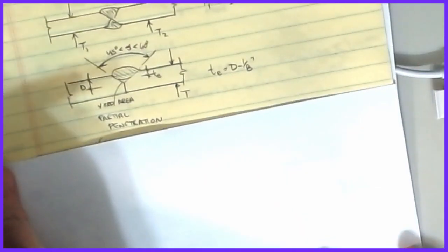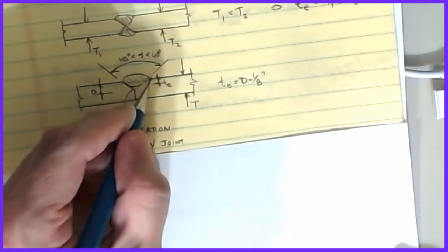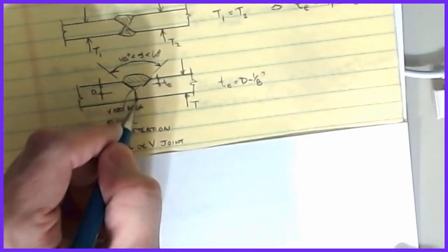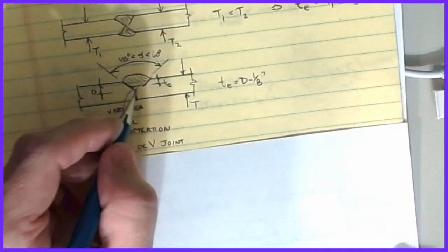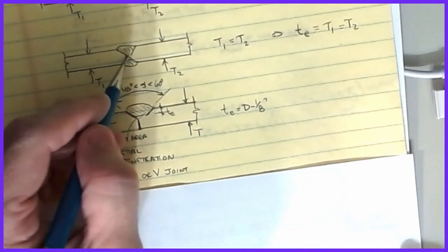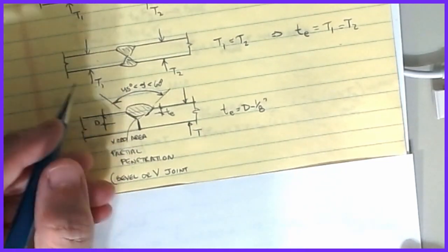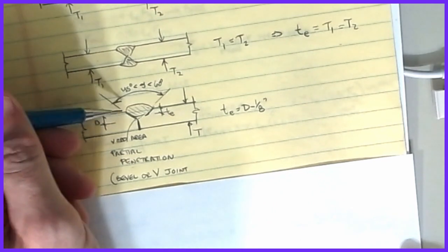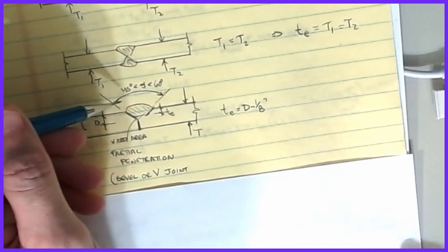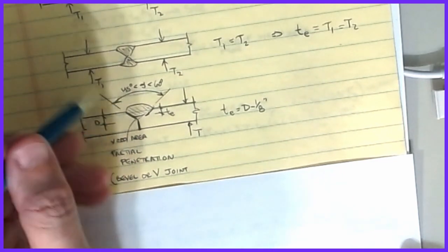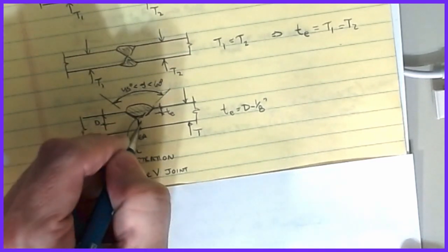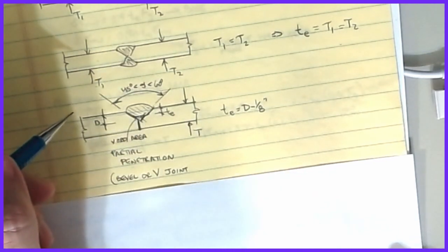Okay, the one that's a little bit different is this last guy, and this is called a partial penetration groove weld. So what we have is kind of a beveled edge, and then it comes in, and then kind of this flush, flat connection here. So there's no connection on the bottom side of this, but it kind of solves the problem that you had here of having to flip the part over, so I can do this weld. The angle of the bevels has to be between 45 and 60 degrees on this. If you get any flatter than that or any steeper than that, then you have some issues. But again, what you're worried about in all of these is that this is an interior weld, and you can get a spot that doesn't get any weld if this thing doesn't form correctly.